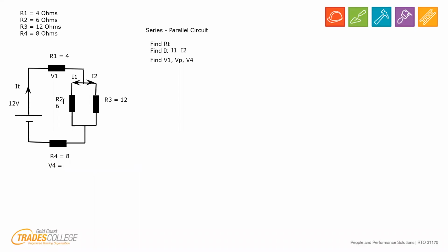And in this area here, now this is a parallel circuit, which means whatever voltage is here is going to be across R2 and R3, because they both share the same cable. All right, the same cable goes in, same cable that goes out. So if there's 10 volts here, then there's 10 volts across R2, 10 across R3. If there's 500 volts there, which there can't be because of the load, but regardless, whatever voltage we work out to be here is going to be the same across the two. And I'll show you how to do that shortly. But I'm just going to write in the center there that VP is where the voltage is going to be.